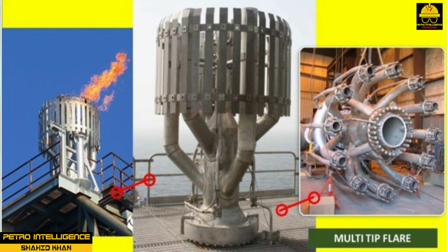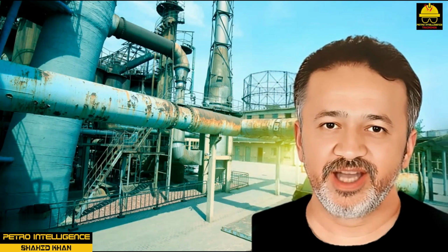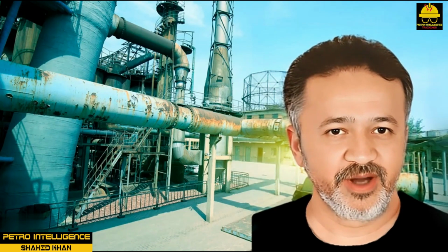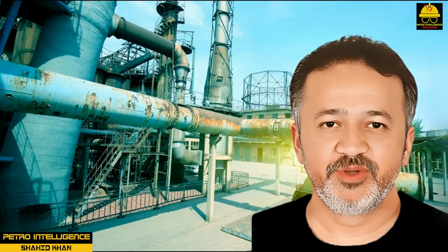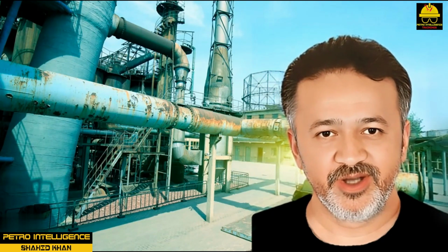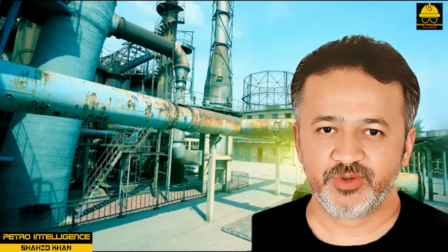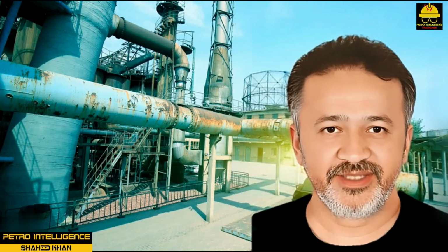The flare tips are equipped with pilot burners to ignite the gas as it flows from the tip. These are always burning, but if one goes out, they can be relit from remotely located flame front generators. Air and natural gas are connected to the flame front generator and are admitted in controlled amounts to form a combustible mixture that flows to the pilot burner through a small, 1-inch diameter igniter line. A sparking device in the mixing chamber ignites the gas-air mixture, and the flame travels through the line to the pilot and lights it. Separate natural gas lines supply the fuel to the pilots.